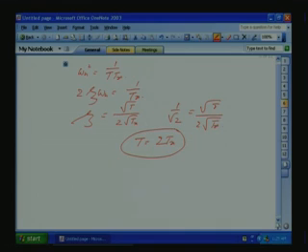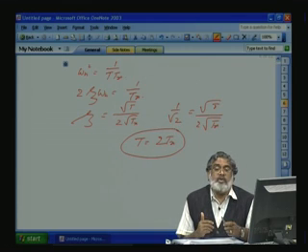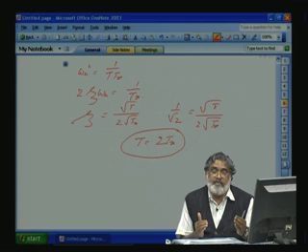Now, see this current loop. In the closed loop control system, we have an outside voltage loop and an inside current loop, and the inner current loop should be fast acting compared to the voltage control, then only voltage control will be firm. Because any change in voltage happens because of the mismatch in the load current and current control.